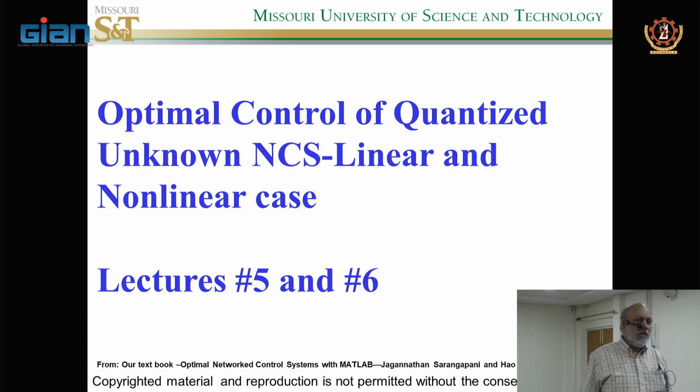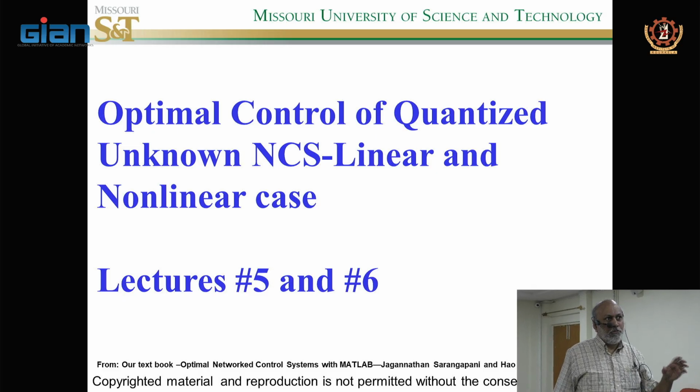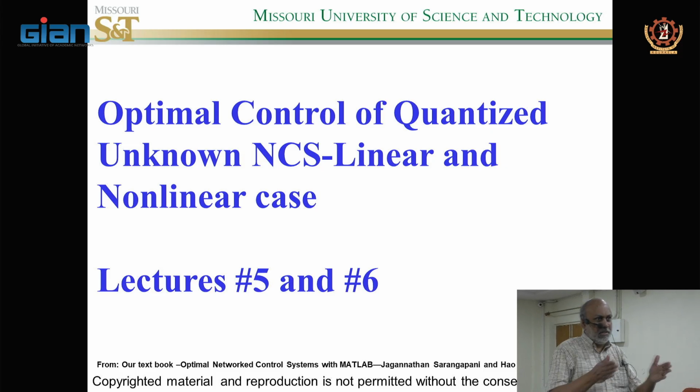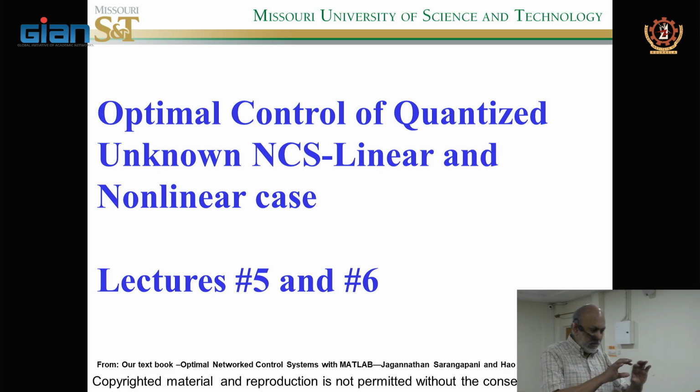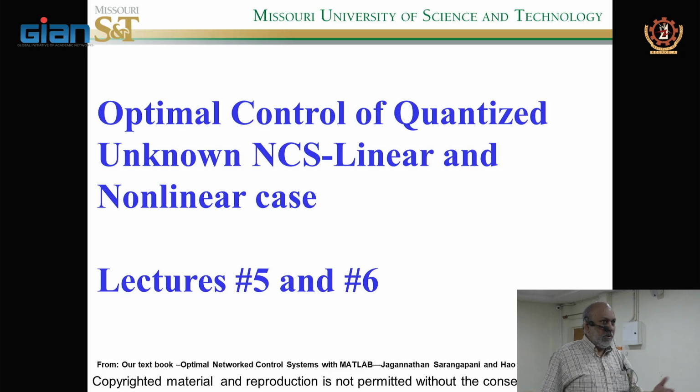But let me say this: the discrete time work we have done connects at least with the learning rates, whereas in continuous time there's no connection at all. If you take a course on continuous time adaptive control, for instance, all those adaptation gains don't give you a bound. In discrete time, at least you have the bounds. For the learning rate, alpha should be greater than 0 and less than something. But in continuous time, you don't have it.